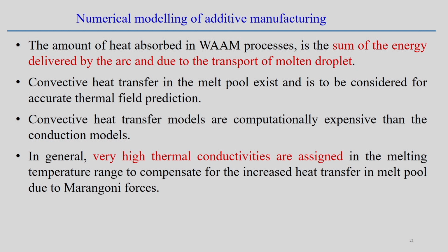So, the total energy has to be counted: one part from the heat source, which can be laser or arc, and another part for the deposited material, because the deposited material is superheated. So, when the droplet transfers to the domain, it definitely carries some thermal energy. Both energies have to be counted when you try to develop this model. I can say it is an important aspect associated with the modeling approach.